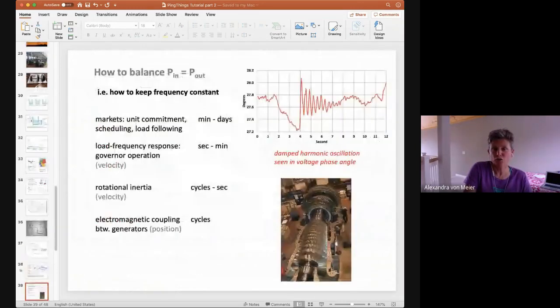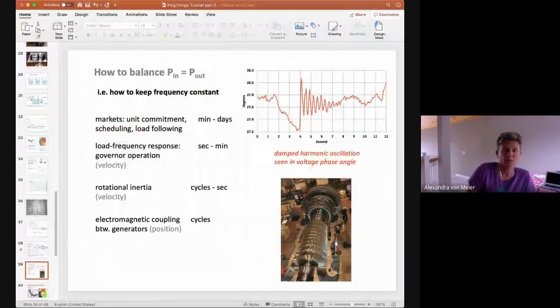I think it's 4:01. I'm going to show you just a couple more pictures on this topic, which is a cutaway view of an actual steam turbine in the front and generator in the back attached to it. And when there are disturbances in the system, you will see this shock load and the twist, a little bit less than a degree, with a damped oscillation returning to a more or less steady state, not exactly steady state.